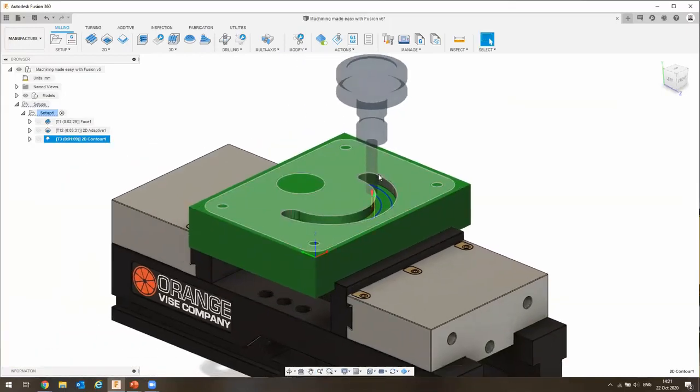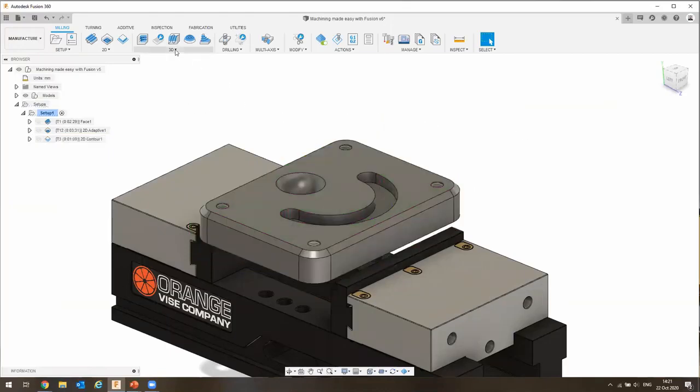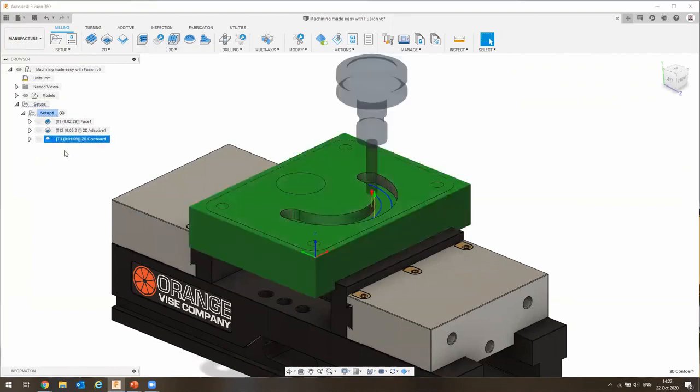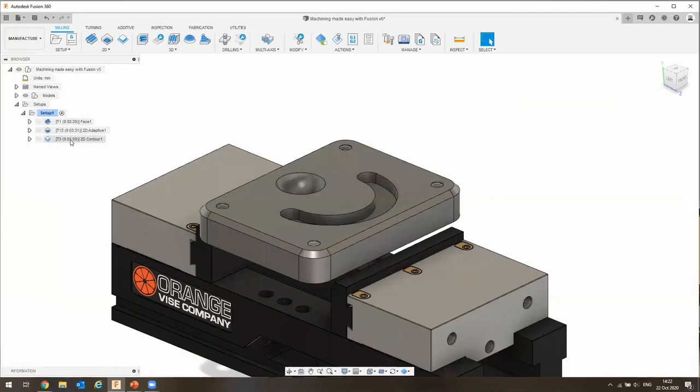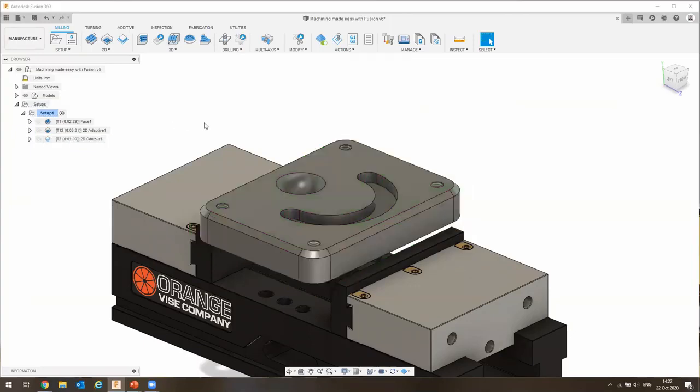Now I'm going to use this same cutter to machine the outside of this shape. So I'm going to use the same thing. I'm just going to switch over here, and you'll notice the whole time the model sort of changes to stock and then disappears. All that's happening there is I'm just deselecting this. I'm not pressing any fancy buttons. When I just press escape or deselect, it'll show you your model as it is, not the machined variant.